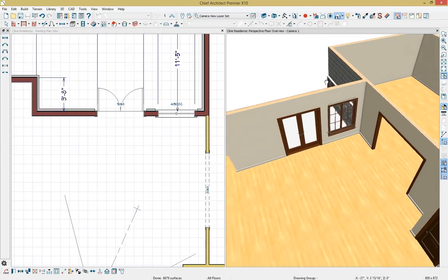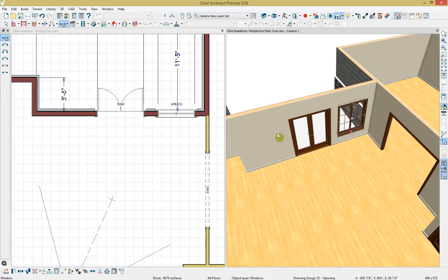And if I want an exact copy of this window to be on the other side of the door, I could place a window right here and recreate it exactly how we had it, but there's a more efficient way to get a copy of this window over onto that side. So with the window selected, in our bottom toolbar we have an option right here for copy, and notice that my cursor changes and I can just click and place a copy now in any of our walls.